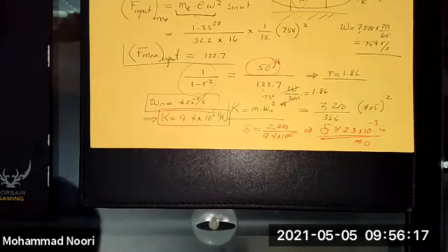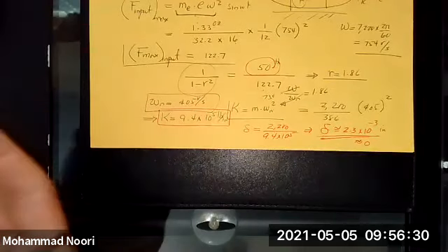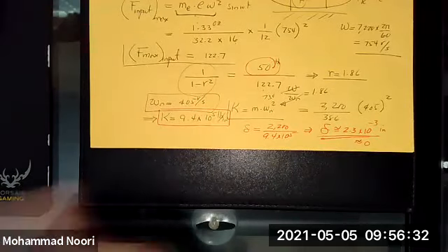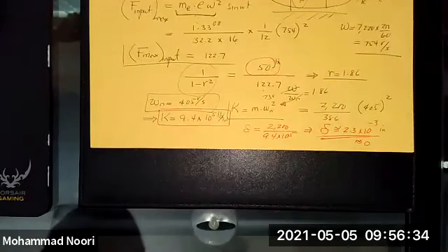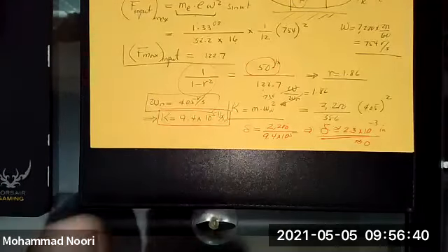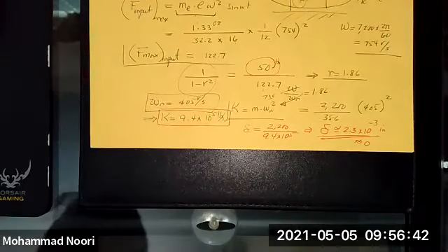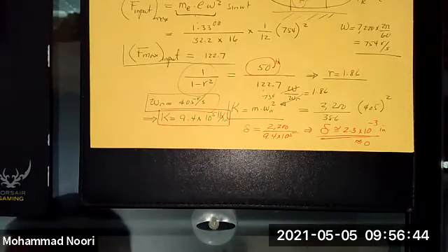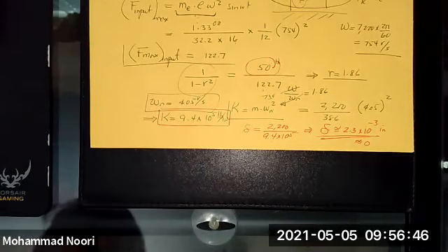Professor, in regards to that, when we're given a mass in terms of pounds, should we just assume that it's pounds mass? If it is pound mass, no, we don't do anything. If it is pound force, you convert it to pound mass, because omega n is square root of K over M, and M is mass. In the good SI units, that's kilogram.